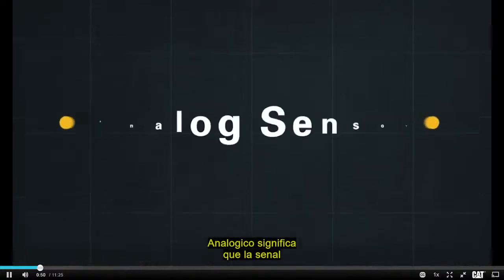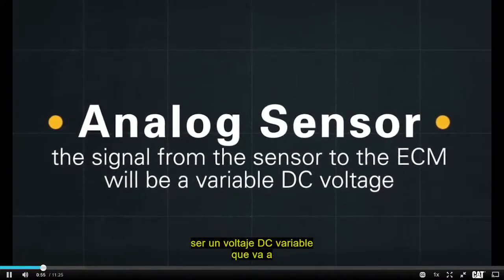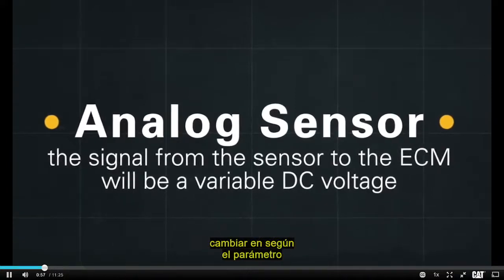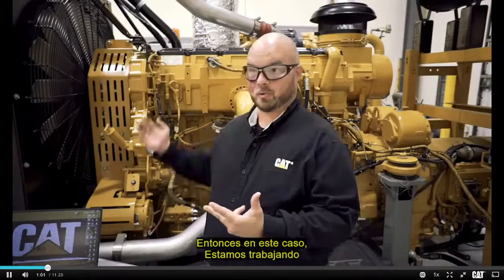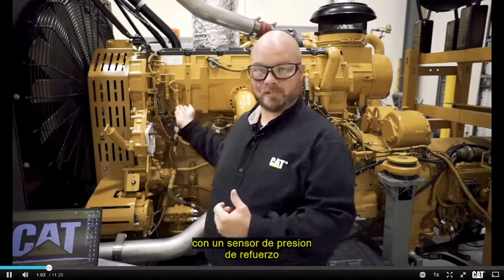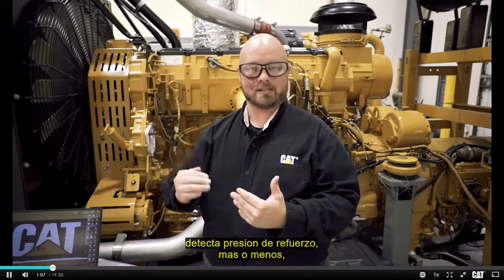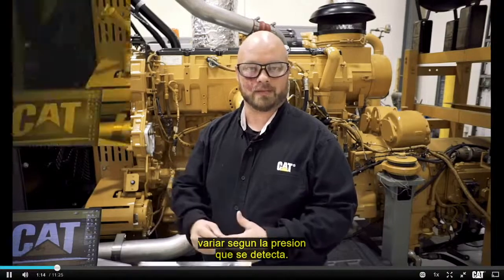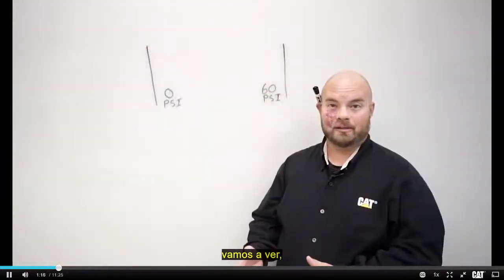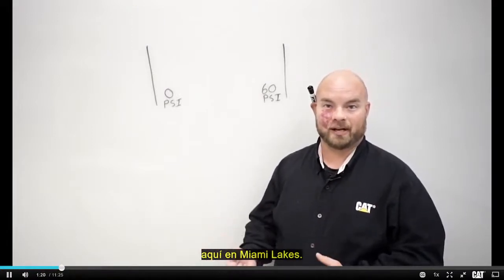Analog means that the signal from the sensor to the ECM is going to be a variable DC voltage that changes based on the parameter being measured by the sensor. In this case, we're dealing with a boost pressure sensor. As this sensor detects more or less boost, the DC voltage coming from the sensor to the ECM is also going to vary based on the pressure being detected. In our example, we're using the boost pressure sensor on that C15 industrial engine down here in Miami Lakes.